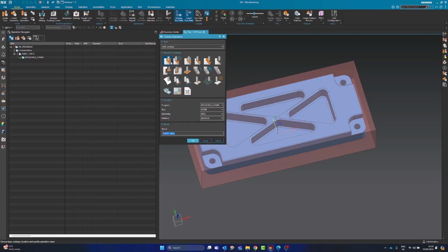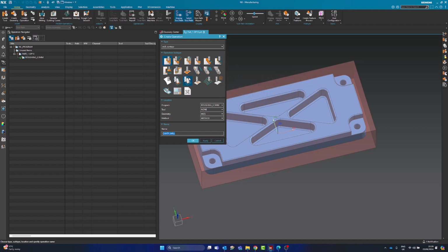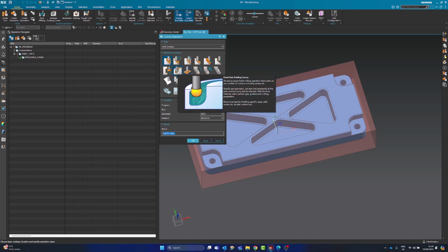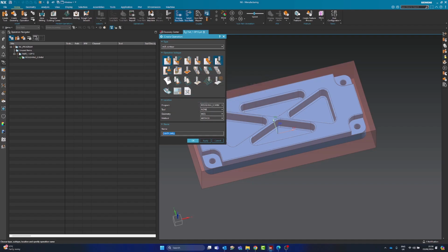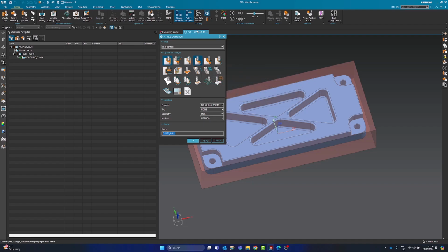Contour is going to be another good one that we're going to use a lot. This is what I would call a 3D toolpath. It's creating surfaces, and you can see here you've got a lot of surfacing operations. Contour area, that's a nice one, really easy to use. Fixed axis guided curves, that's one of my favorites, really universal. You get some lovely toolpaths using this. Z level undercuts, your Z level profile, quick roughing. We can take a look at all this stuff in good time.